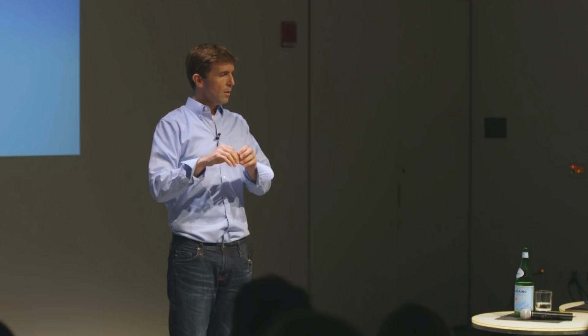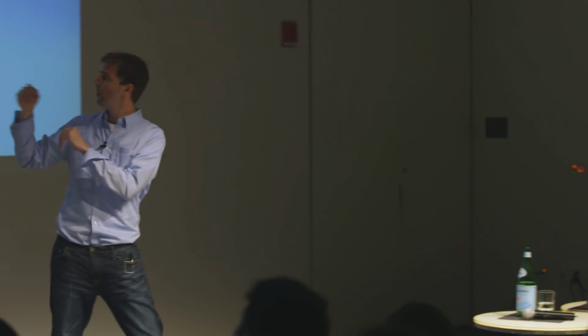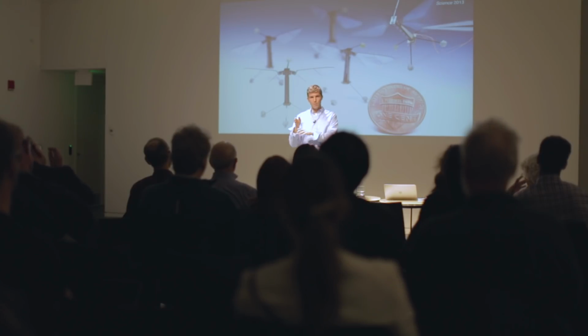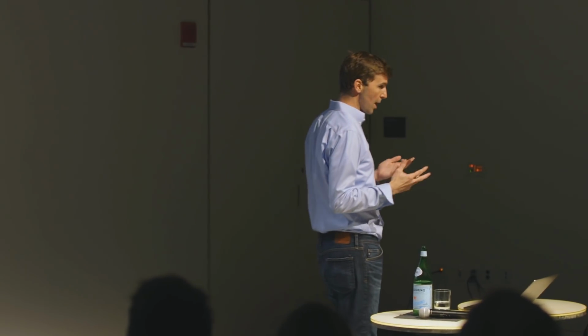So anyways, we actually use a lot of passive modes in these devices. One of the passive modes is this rotation. We actuate this motion and allow this to be passive and just tune. This is mediated by a little flexure hinge, a little fold at the base of the wing that you probably can't really see here. By tuning the inertia of the wing, the axis of rotation of the wing, and the stiffness of this flexure, we can get these quasi-static rotation modes tuned to the appropriate phase relative to flapping to generate optimal lift. And after we did this, we looked back at the biological literature, and there's a lot of evidence that flies do the exact same thing.